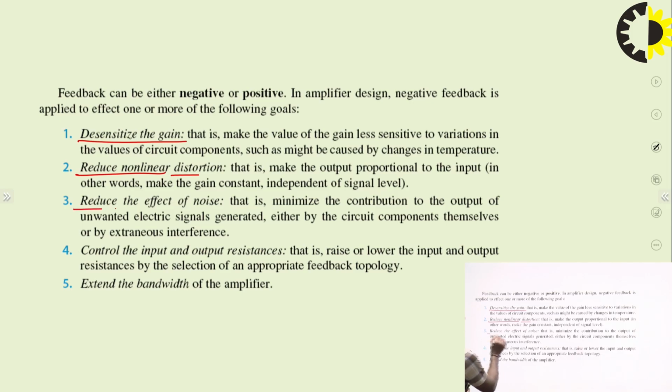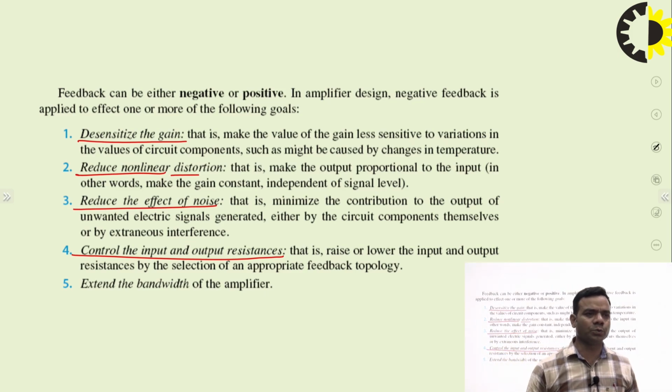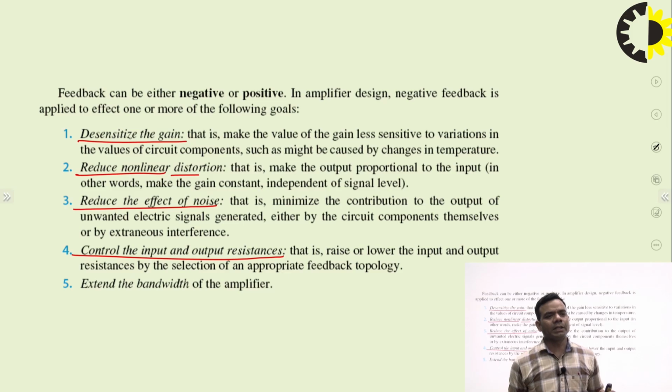Next, it reduces the effect of noise. It minimizes the noise. We will see how it can minimize the noise. It controls the input and output resistance. That means if you want the input impedance to be high, you can choose the proper negative feedback topology.